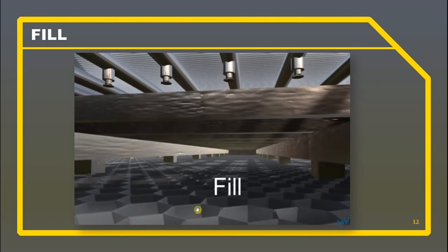On the fill, a thin film of water is formed on the surface. While the hot water is dripping on the surface of the fill, evaporation will occur due to the air in the surroundings. The larger the surface area of the fill, the more intensive is the evaporation of water, and the more efficient is the cooling tower.